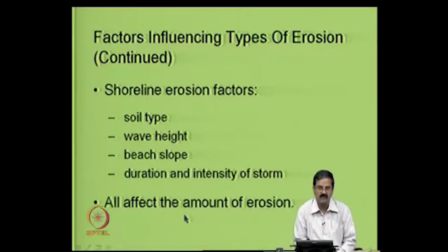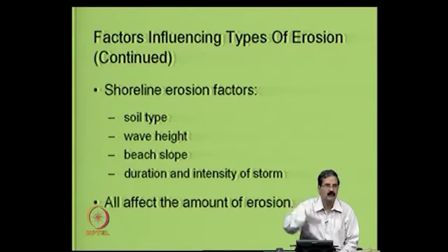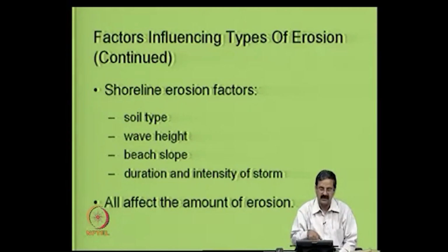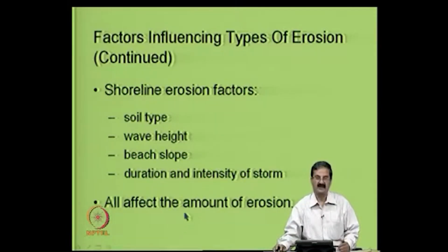In fact, there is a lot of work going on nowadays, because tsunami awareness has come, and the tsunami straight away hits the shores, and if you do not design the slopes or the retaining walls properly, it is very risky. One can design a slope based on the type of tsunami and the wave height. Tsunami generates waves, and if you know the height of the wave, you can design the height of the retaining wall, and its base should be strong. There are so many issues there. Some of these things can be properly understood based on these factors.